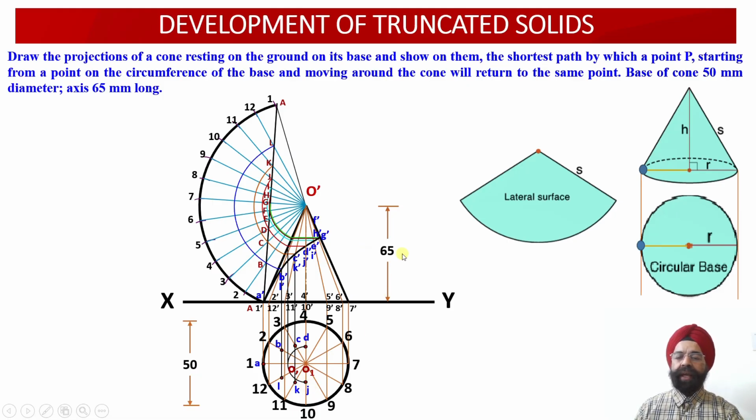So this way, by looking at the solid from the side view, obtaining the radius corresponding to this height, and transferring this radius into the top view projections, we have been able to locate 2 points of intersection D and J in the top view projections over here.